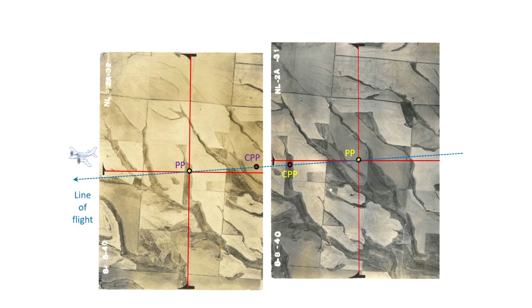Now, if you have the complete understanding of the line of flight, that there is slight deviation over here in terms of the photograph. Okay. So when you mosaic it, it will be easier for you to identify the way, and then you can have the complete 3D view. Okay. And if suppose you are not aware of that, then you will usually try to match this edge and this edge to view the 3D, but that will not be possible to see. Okay. So the line of flight can be done like this.